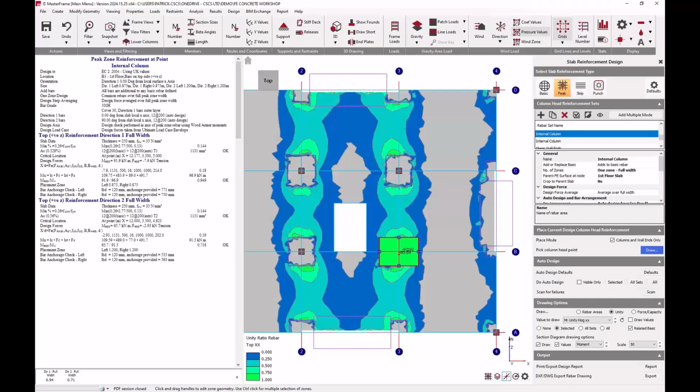Can FE analysis be used for rib slabs? Yes, you can specify isotropic, orthotropic, layered, and even rib FE surfaces in MasterSeries. Although with those types of slabs, you won't be able to do your slab design with the slab design module.